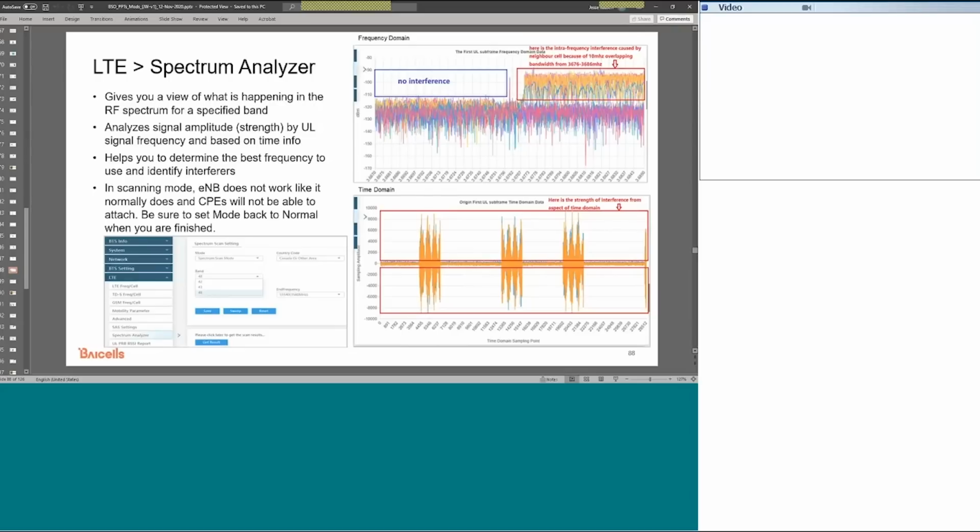So you can see if the first uplink subframe looks clean, but the second one has noise, that there's potentially, for example, some timing issue, maybe the wrong configuration used, or some other neighbor base station out of your control on a different config. This is helpful if you're dealing with performance issues and trying to narrow down what potentially could have some interference or not.